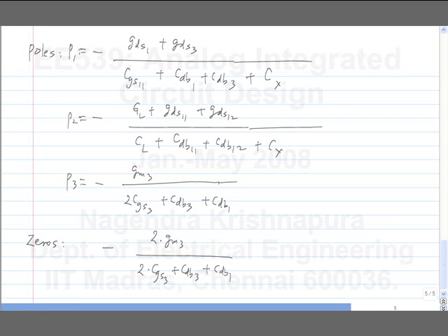Obviously, let's say I choose to do this. Okay? What will be the unity gain frequency? What's the limit on the unity gain frequency? So let's say I choose to just make P1 to very low frequency. What is the limit on the unity gain frequency I can get? Huh? No, but what is the limit? What is the ultimate limit? How can I evaluate the limit? I have to make Cx large enough for it to be stable. So what is the unity gain frequency I am going to get at that point?